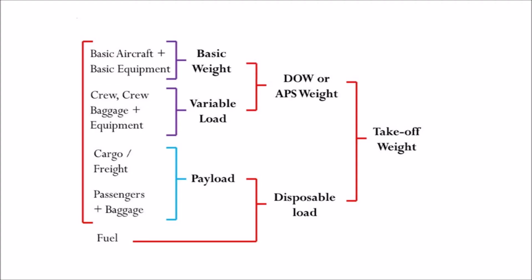Standard empty weight is the weight of a standard airplane, including unusable fuel, full operating fluids, and full engine oil. Basic empty weight is a standard empty weight plus the weight of optional equipment. Useful load is the difference between ramp weight and the basic empty weight of the aircraft. The mean aerodynamic chord, abbreviated as MAC, is a chord of imaginary rectangular airfoil having the same pitching moments throughout the flight range as that of the actual wing.